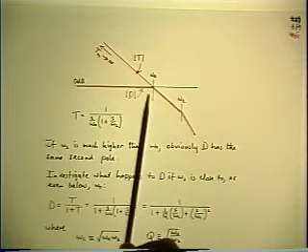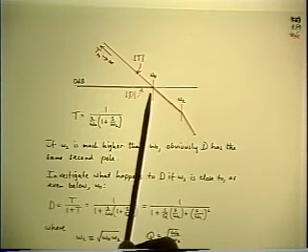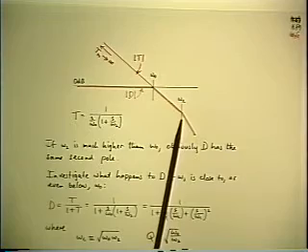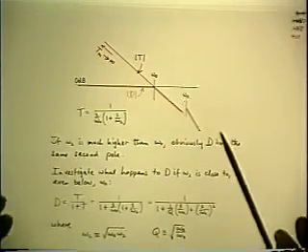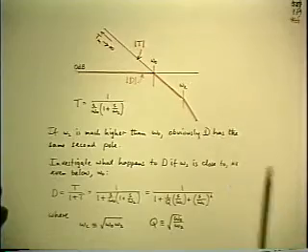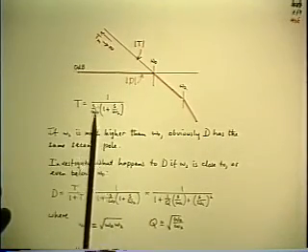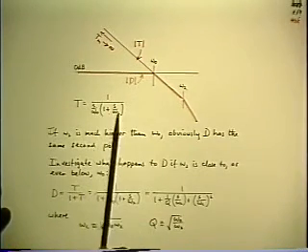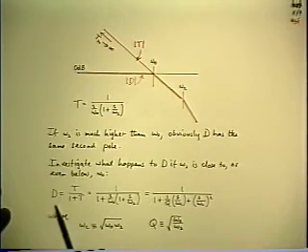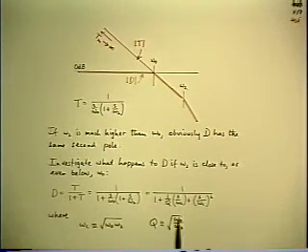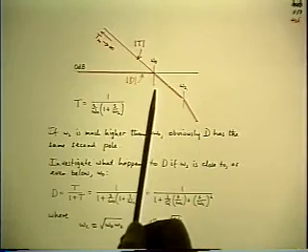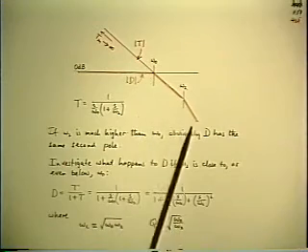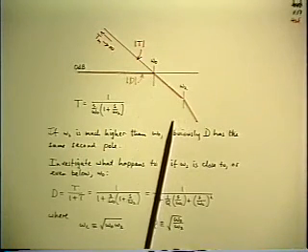Now, if the second pole is a long way above the original crossover, then D is equal to T whenever T is small, so D will have the same pole that T does. And here's the formula for T: the original single slope crossing unity magnitude at omega 0, and then a second pole at omega 2. Now, qualitatively, again looking ahead to the result, this is not quite such a graceful roll-off for D, because it's going to roll off a little more rapidly than before. What's the phase margin now?